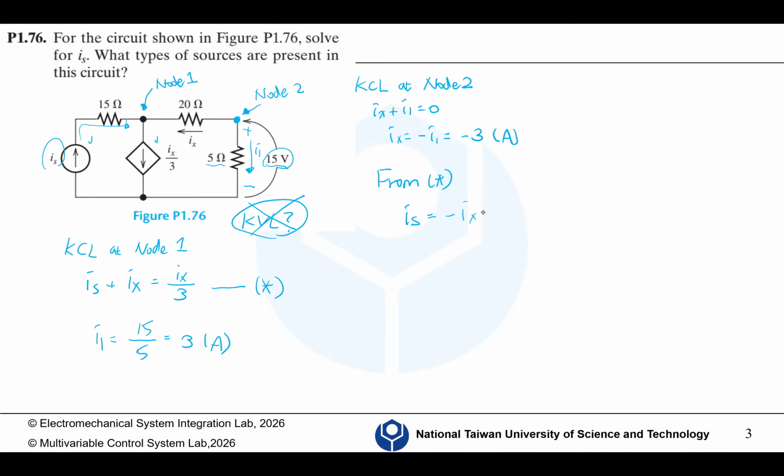By rearranging this, you are able to find 3 equations: 0.35 V1 minus 0.2 V2 minus 0.05 V3 equals 0, and minus 0.2 V1 plus 0.30 V2 minus 0.1 V3 equals 10, and you have 0.05 V1 minus 0.1 V2 plus 0.35 V3 equals 0.